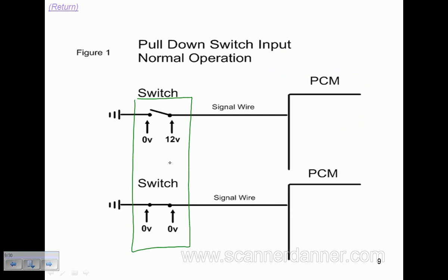This is why it looks like that. Internal to the computer, if you wanted to add this, you'd have a resistor and you'd have a source. In our case, this time it's 12 volts, and you'd have some type of voltage sensing circuit inside of that computer. That's what that would look like. I left it out of there intentionally this time because when you get to real wiring diagrams, this isn't there. You need to be able to visualize what's inside that computer.